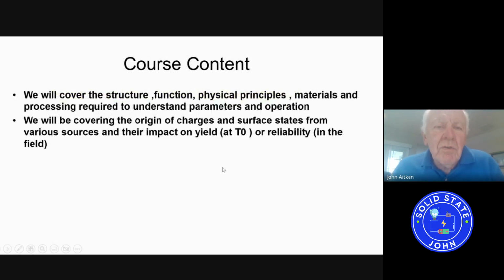The content of the course in broad outline is presented here. We'll cover the structure, function, physical principles, materials, and processing required to understand FET devices and parameters. We'll be covering the origin of charges and surface states from various sources and their impact on yield at T0 or reliability in the field.